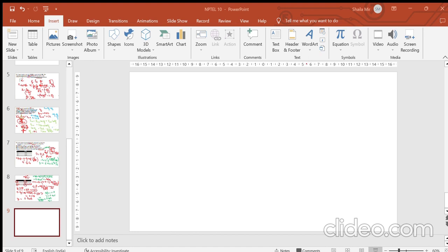So higher dislocations mean higher strength in the material, because you will be able to work harden it. These dislocations have a pinning effect inside the material, and that pinning effect will prevent grain growth, prevent deformation, and prevent fracturing from occurring. So dislocation is favorable for a higher work hardening effect.